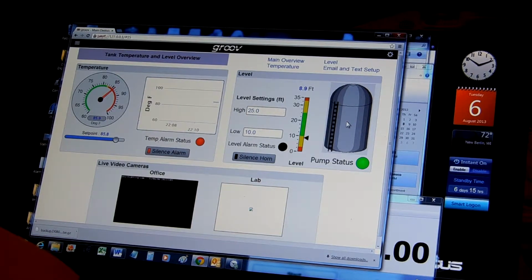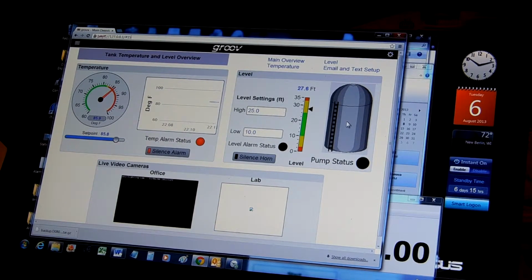Here in my office, I have an Opto22 controller connected to a training panel with sensors and switches and buttons and knobs and lights, and I can control the level of the tank with a rotary pot. When I raise the level of the tank far enough, the pump turns off. You can see there's a pump status LED, and when the tank level drops down too low, the pump will turn on again to start filling the tank. There you can see the pump status turned on. So that's what I have here. I can adjust the temperature as well. There's a PID control that's maintaining temperature.